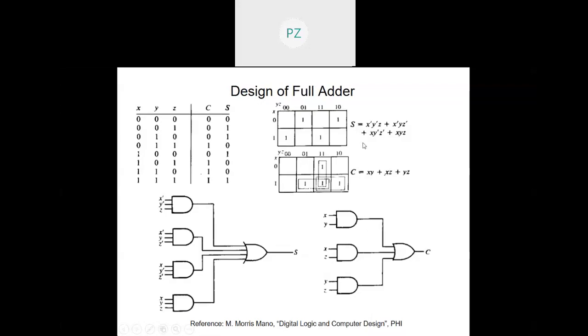Now, coming to full adder. In full adder, I also have the carry in bit. So that way I have 3 bits now as the inputs. So X may be taken as the carry from the previous stage, and these may be the 2 bits to be added. Okay. So let us take the truth table. The truth table should have all the possible input combinations.